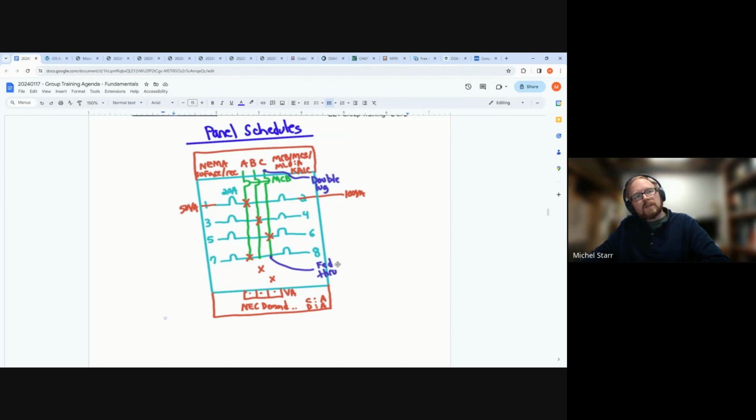It's just wired through and connecting to these bus bars, and then having more breakers to expand the number of branch breakers, because after you get past 42, it starts to just be a consideration. So you get up to 60, if you get up to 84, the depth of the panel board and wire bending space just starts to be a little tight, and then considering these buildings, you're building a building that might want to be around 30, 40, 50, 100 years. So just using sensibility in this, and knowing it's easier for the installers too, to try and split them up.